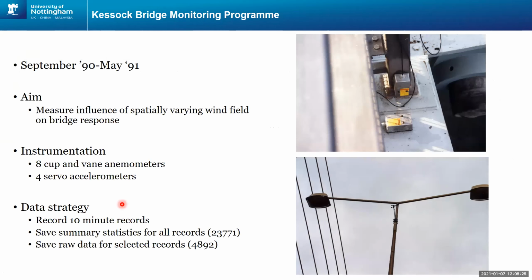So this is quite an old monitoring exercise. Indeed, it's the exercise that first got me into wind engineering. It was between September 1990 and May 1991. And we were basically looking at measuring the influence of spatially varying wind field on the bridge response. We had some very rudimentary instrumentation. We were just using cup and vane anemometers, 8 of them, which were located principally on lighting columns down the center line of the bridge.